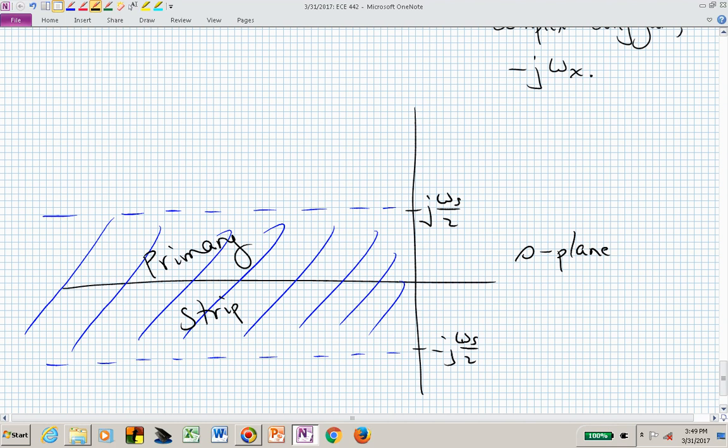But suppose that we're walking up this imaginary axis in the S-plane, and we now say, what happens if we actually sample at this particular location? Or what happens if we now had a pole even? Let's say that we had a pole at this location, and that location splits equally the distance between omega sub s over 2 and omega sub s.